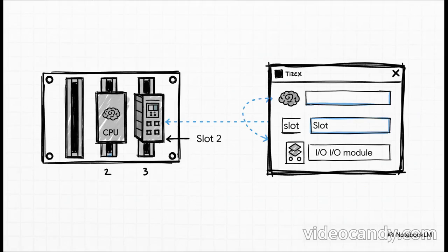Now for the final setup piece in Studio 5000. When you create a new project here, you have to be really precise. You'll need to select the Logix Emulate controller type, make absolutely sure the version matches, in our case V30, and tell it that it's in slot 2. Then, you'll add a new module to the project's I/O tree to represent that card we put in slot 3. Everything has to mirror your virtual rig perfectly.